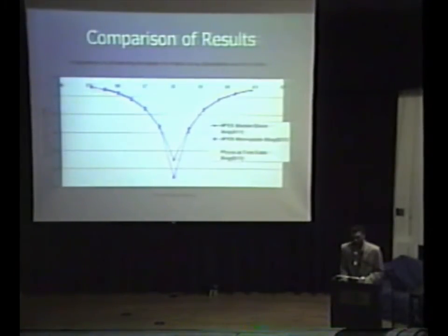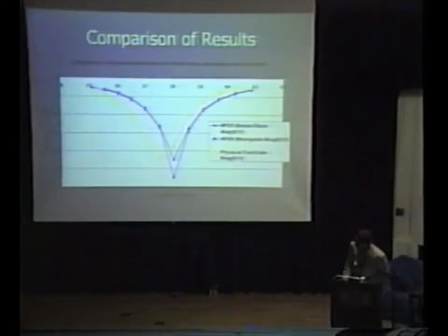At higher scan angles, you're actually getting worse matching. But I don't typically think that the 6 dB point is taken as the bandwidth of a patch antenna. I think it's usually taken around 15 or 20 dB for optimal operation. Well, that's not at normal incidence. That's at an angle. The incoming wave would be approaching the array at an angle. If it was normal to the surface, it'd be around 35, 40 dB.